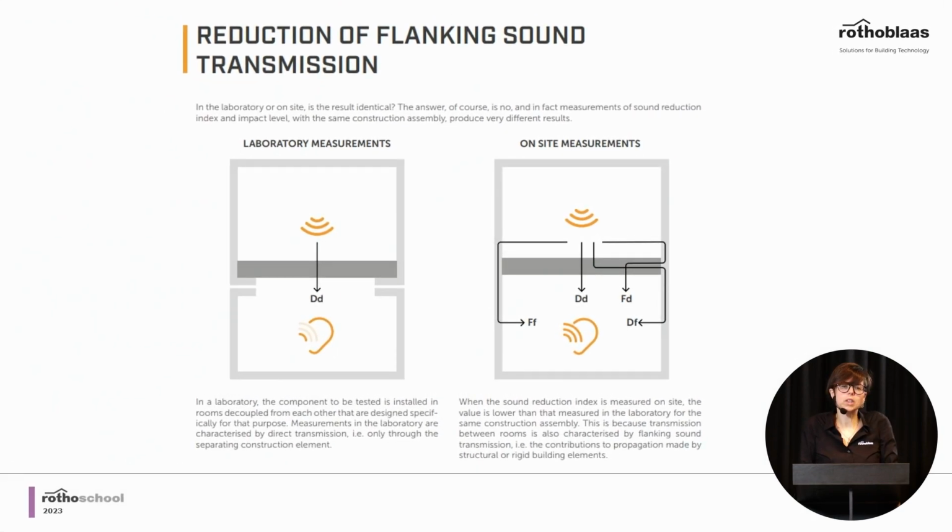So what is flanking transmission? When we do a measurement in the laboratory, the measurement is done in a way that what we are measuring is only the performance of the partition, for example, of the separating wall, because the laboratory is set up in a way in which the structure is not connected.